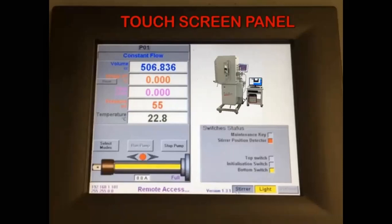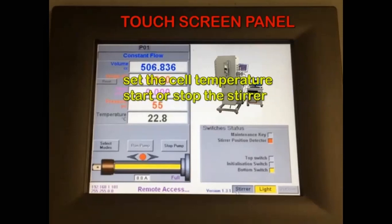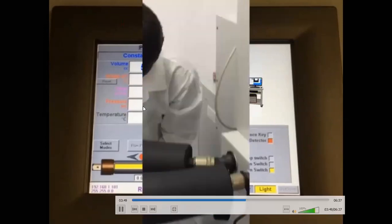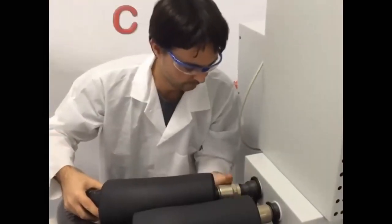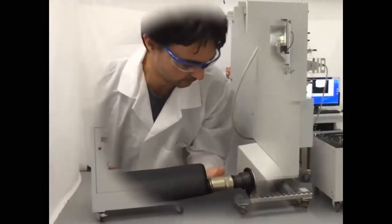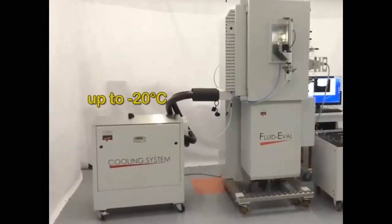Control the instrument locally. Specifically, the operator can set the cell temperature, start or stop the stirrer, set the position of the PVT cell, and select the operating mode of the embedded pump. A cooling unit can easily be connected to the air bath to provide sub-ambient temperatures of up to -20 degrees Celsius.